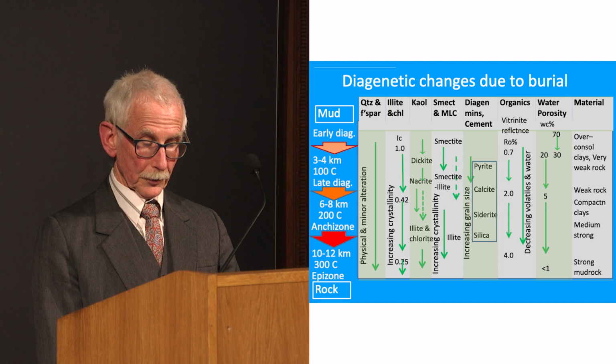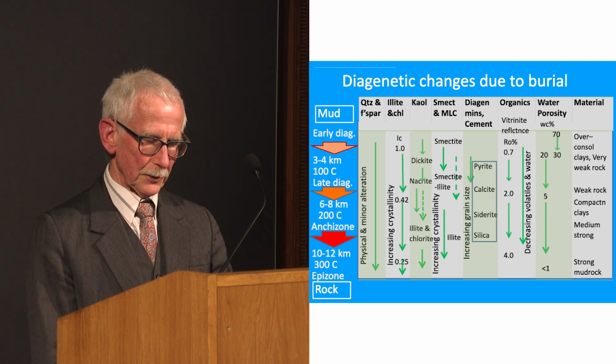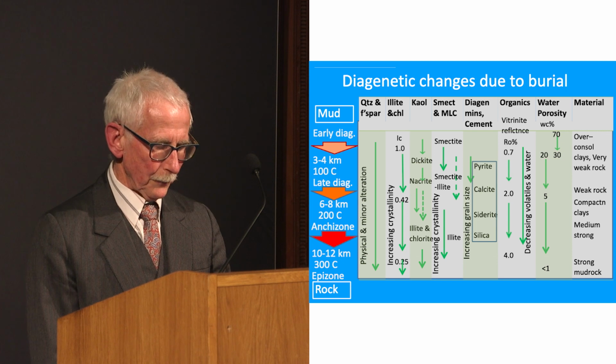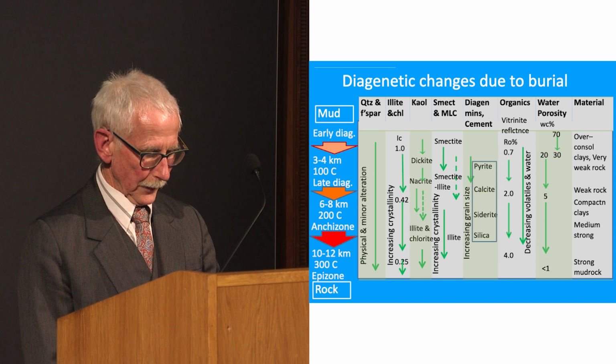In clay-rich rocks, the bonding will be slower to form, and the clay is likely to be oriented perpendicular to the major stress, which in this case will be vertical, making the material anisotropic.